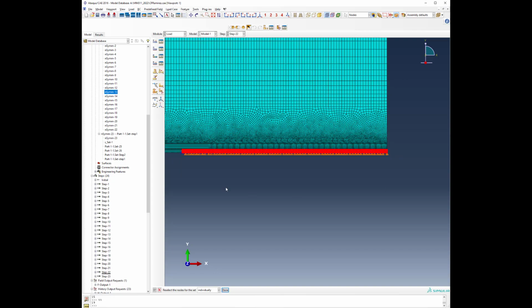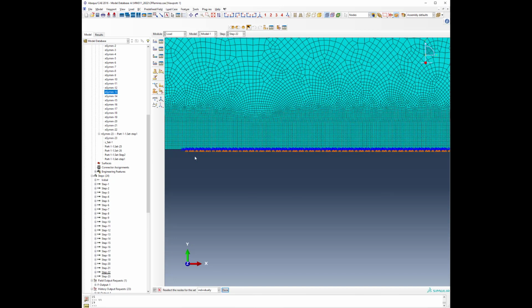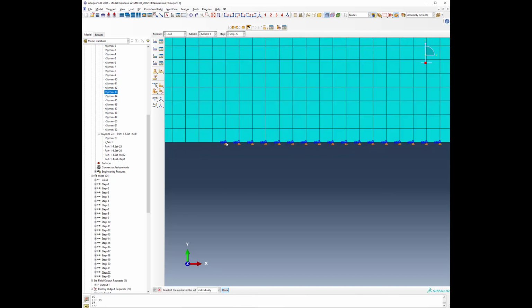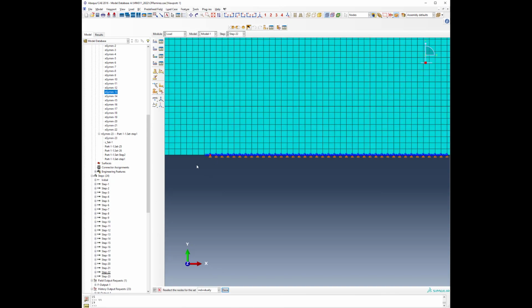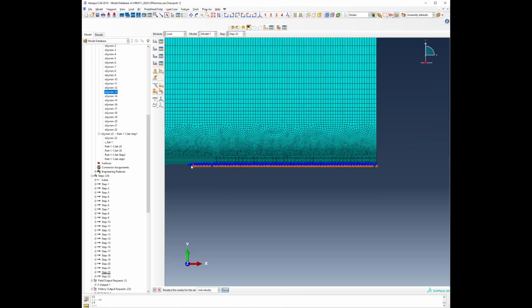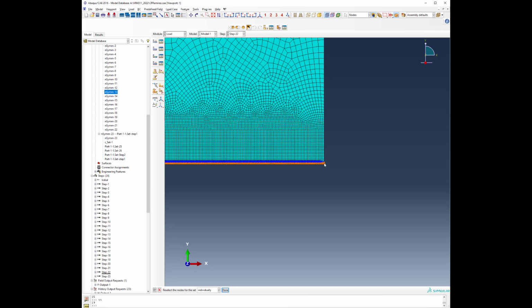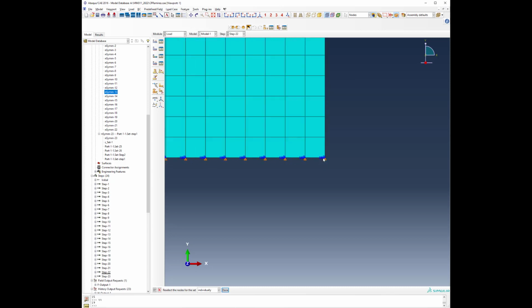Okay, so for instance, in this case the crack tip starts from here, so we take this as xe plus tt times the element size, and then it goes to a maximum value of the x coordinate so that the whole ligament is covered. And for the y coordinate, there is no extension because you are selecting only nodes on the crack plane.